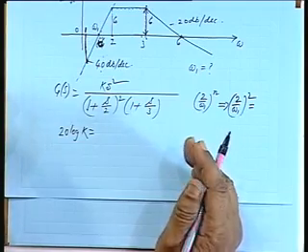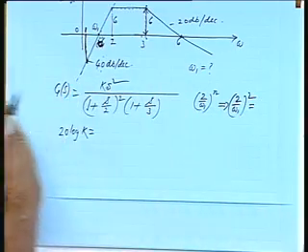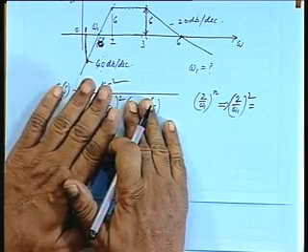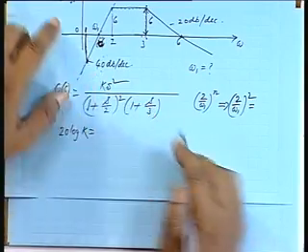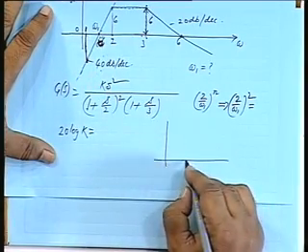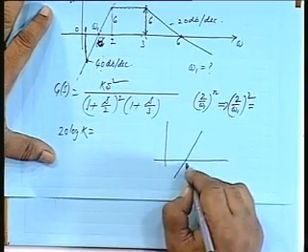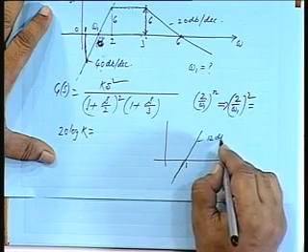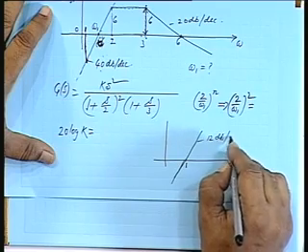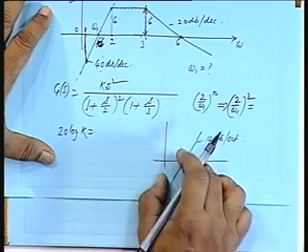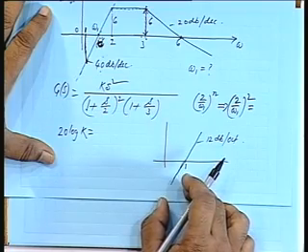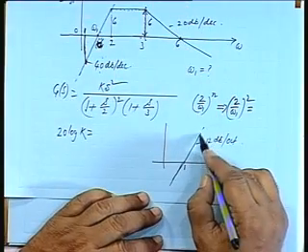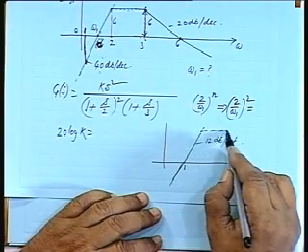Normally when we compute, these are all asymptotes. So at a very small value of s, this does not figure, this does not figure. So it is k s squared. Had it been only s squared, it would have started like this. At 1 it would be 12 dB per octave or 40 dB per decade, is it not? Now, this has gone down by 6, it is here at omega equal to 1. Otherwise it would have been much above this.